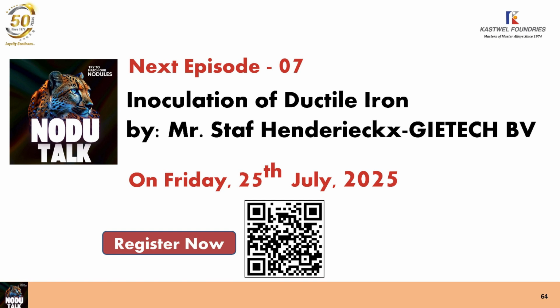First about the calcium, I should say use a fixed amount of calcium, let's say in your nodulizer. Then you will find out what the reaction is and how much you have to treat the slag to get it out. But if all at once you use a much higher calcium, you will have much more slag. And then all the technique and the procedure your people used for removing the slag with lower calcium will not be a good result for the higher calcium. So try to stay with the same amount of calcium all the time.